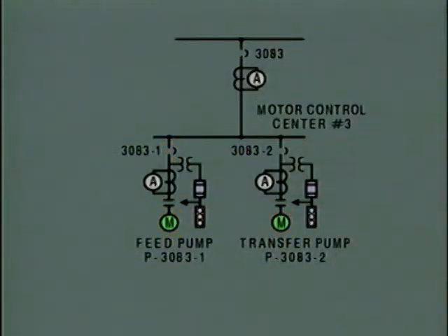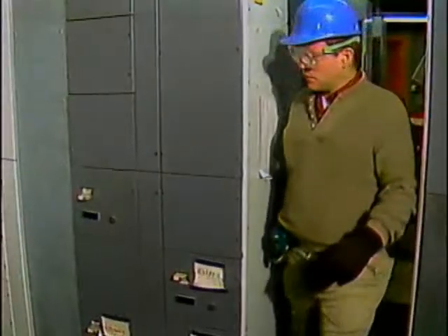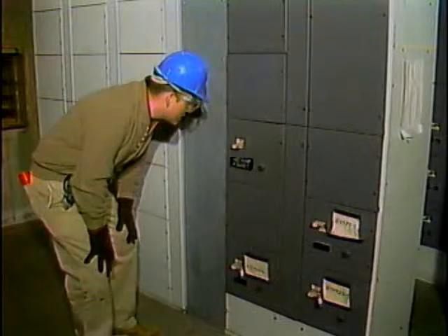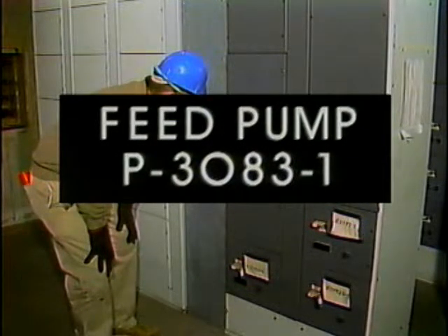In many cases, components represented on an electrical one-line diagram are numbered. The diagram we've been working with shows how component numbers may appear on a diagram. You can use the ID numbers to verify that you've found the right component by matching the number on the diagram with the number on the component in the plant.